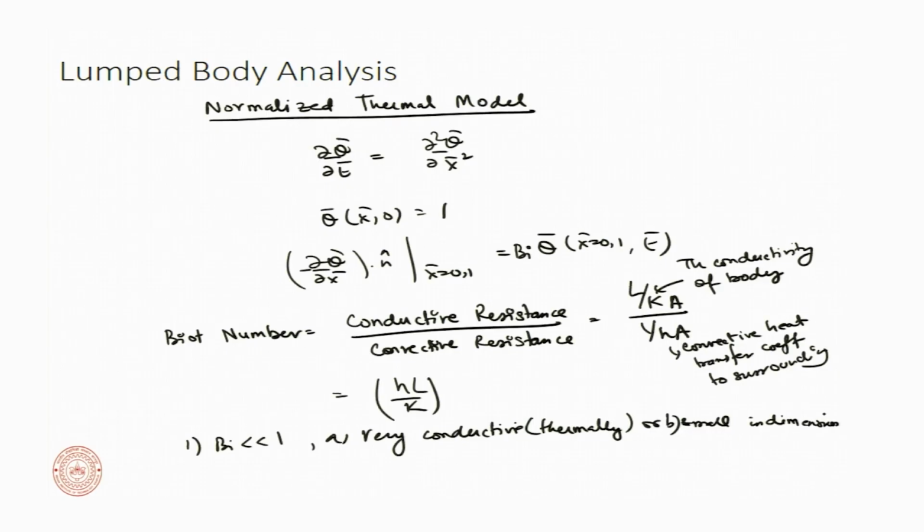Okay. So a small body, a thin body, for example, if I compare this pen to this, and the effective length is this much, say this is around 2 centimeters and this is around 5 to 6 centimeters, right. In these cases, this will have a lower Biot number if these are of the same material, I am assuming. This body will have a lower Biot number compared to this body. That means that the heat can diffuse or dissipate via conduction very quickly in a thinner body compared to a thicker body. Okay, that is one.